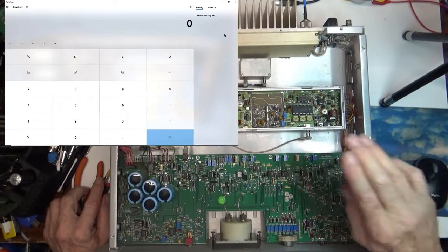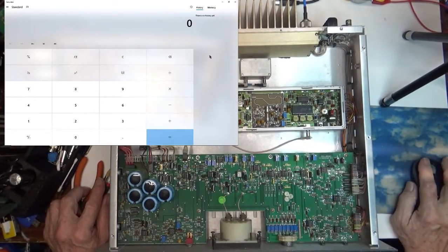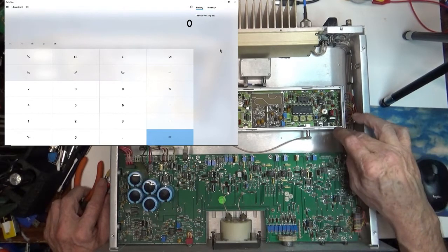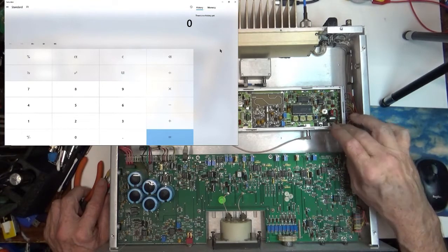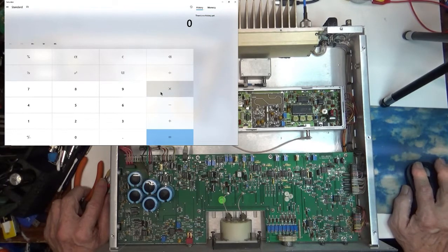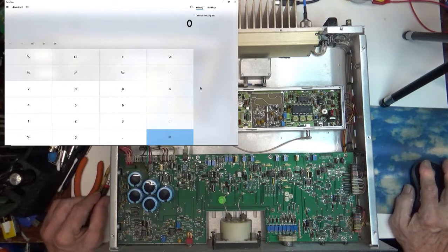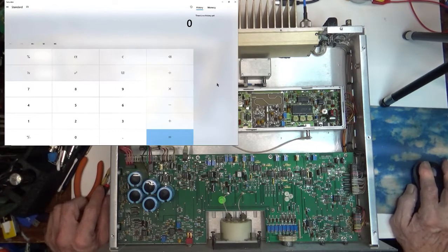In order to set these switches for the frequency that you want, the correct procedure is to subtract the frequency that you want out of this. Right now this is on 944.5. You subtract the frequency you want from 1020, or 1.02 gigahertz, which we'll do on the calculator.